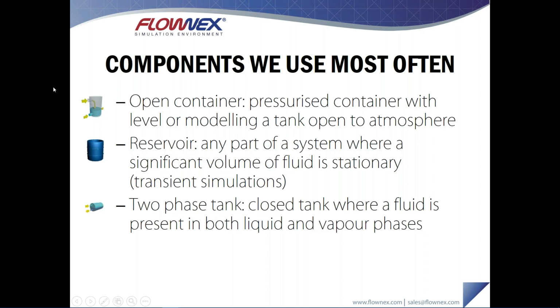This is a component that I like to use when modeling some sort of pressurized container with a level inside of it. If you have, say, a pressurized container with water and steam, it's not the component to use. In that case, I'd use a two-phase tank. That's ideal for modeling liquid and vapor phases in the same container. But if you have a container with, say, water and air above it, and the container is pressurized, use an open container. It has an option for free surface pressure, and it can get you out of modeling an entire air system.